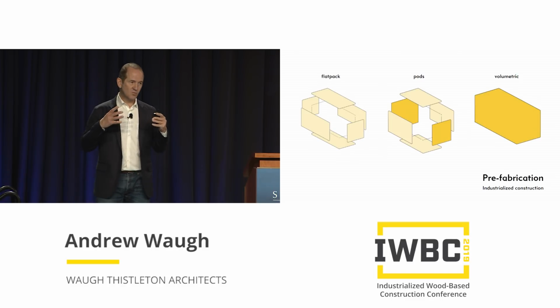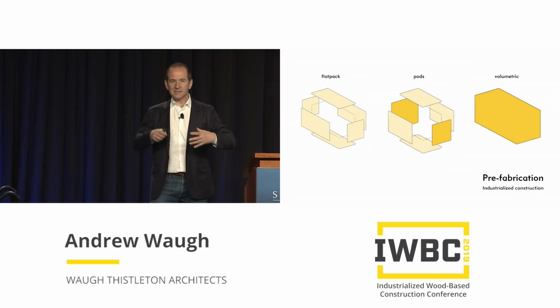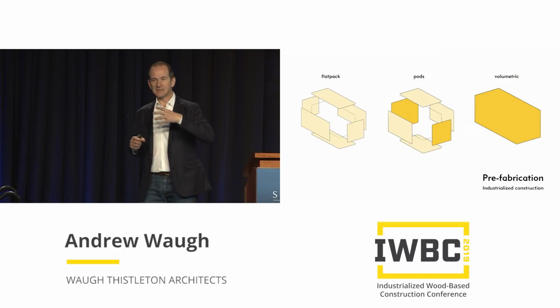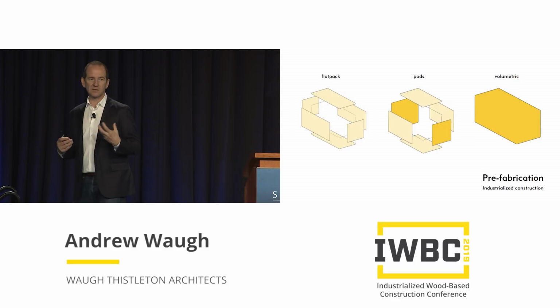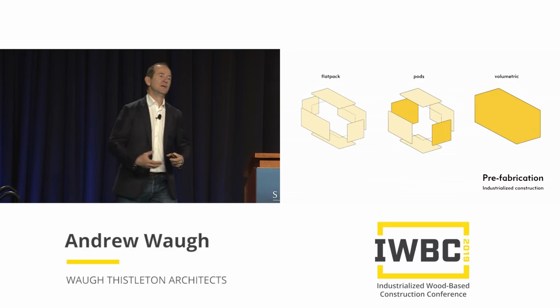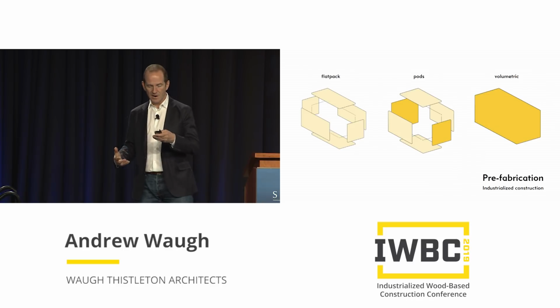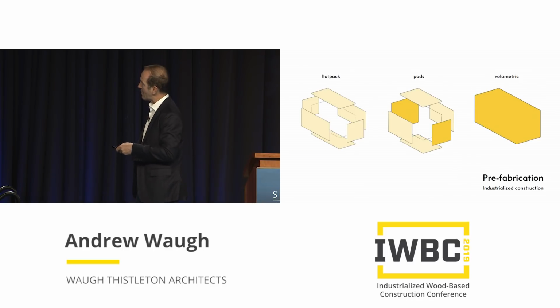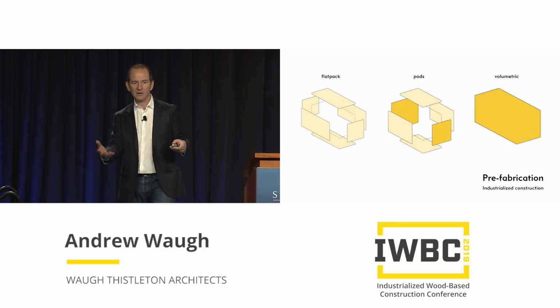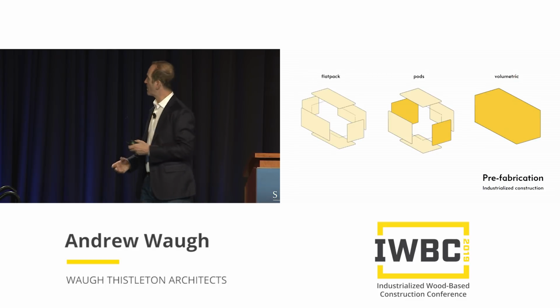So we've begun to realize that part of our process of building in timber is this idea of the industrialization of the construction process. And industrialization means better quality, less risk, better security and confidence in terms of price and program. So we started that journey with flat pack, building in CLT panels, putting them on the back of a truck from a CNC factory, taking them to site, screwing them down into position.